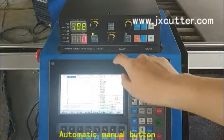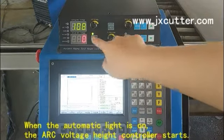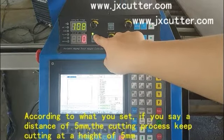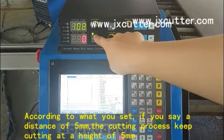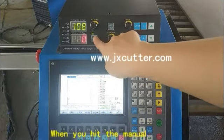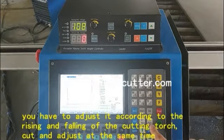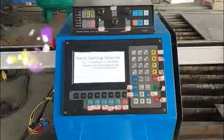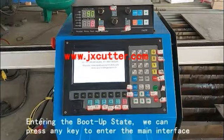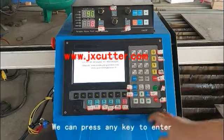Automatic manual button. When the automatic light is on, the arc voltage height controller starts. According to what you set, if you set a distance of 5 mm, the cutting process keeps cutting at a height of 5 mm. When you hit manual, you have to adjust according to the rising and falling of the cutting torch. Entering the boot up state, we can press any key to enter the main interface.